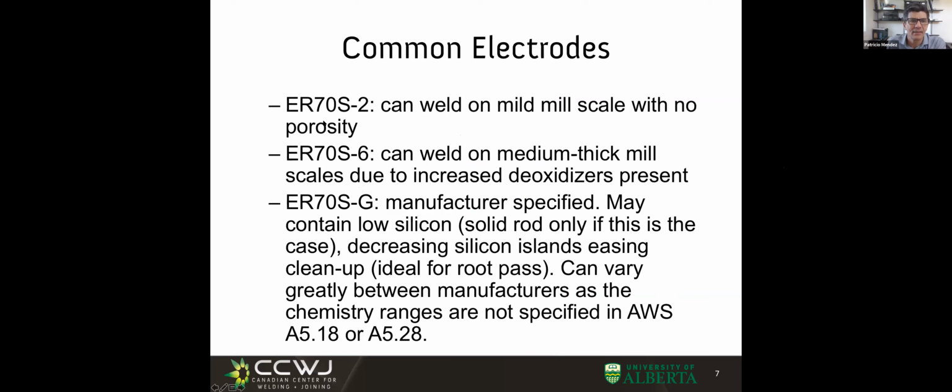And so here we go. I have in this slide where we talk, S-2 is when we want to weld when there's no scale or no porosity, or when we're making many passes. Because even if the plate was rusty, after we made the first few passes, we'll be welding over the clean metal of the previous passes. Anybody has a thought of what would happen if I use ER70S-6 over clean plate or after many passes? So let's say I have ER70S-6 and ER70S-2 in welding in very clean plate. Which would be harder? Which would be stronger? Thoughts?